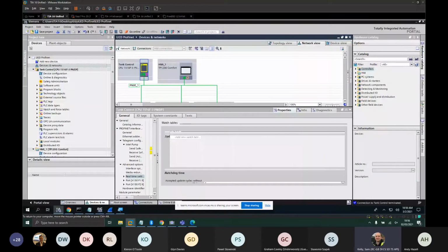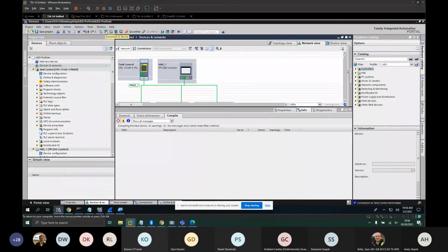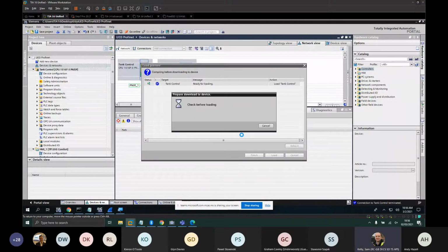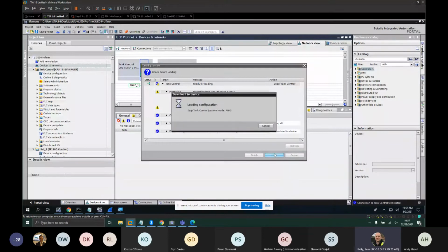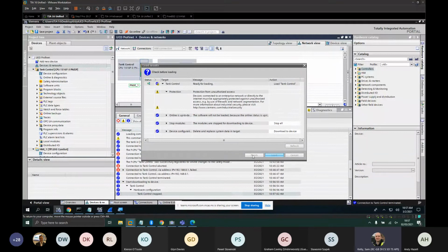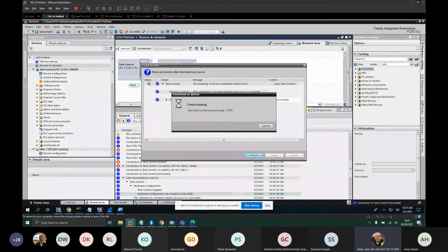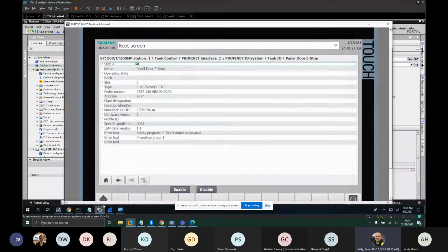So now let's just compile that and download that to the device. So now hopefully we've increased that update cycle to more than 200 milliseconds. Now when we disconnect one of the cables, we shouldn't lose our set point. We'll still have errors on the PLC because we're breaking the MRP network, but most importantly, our process, our functionality remains the same. So let's get the inverter turning again.